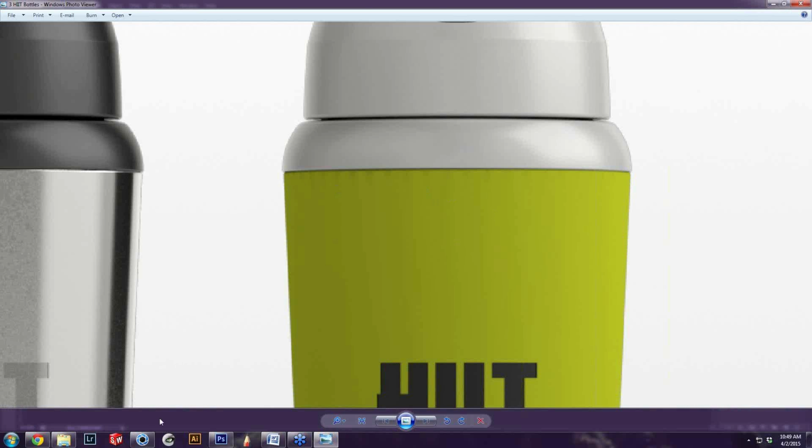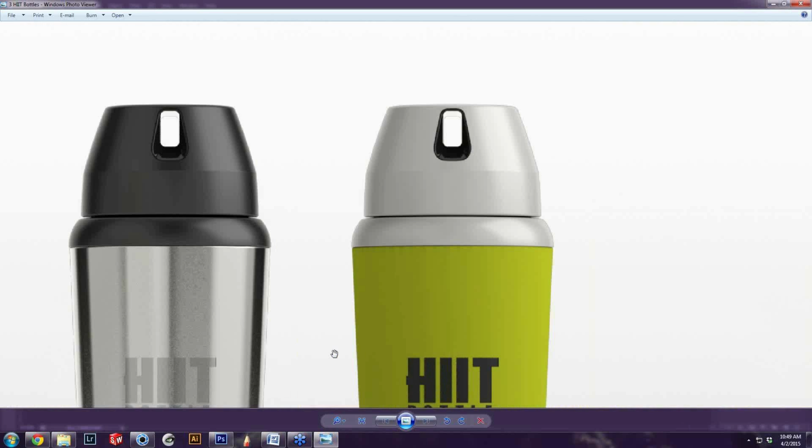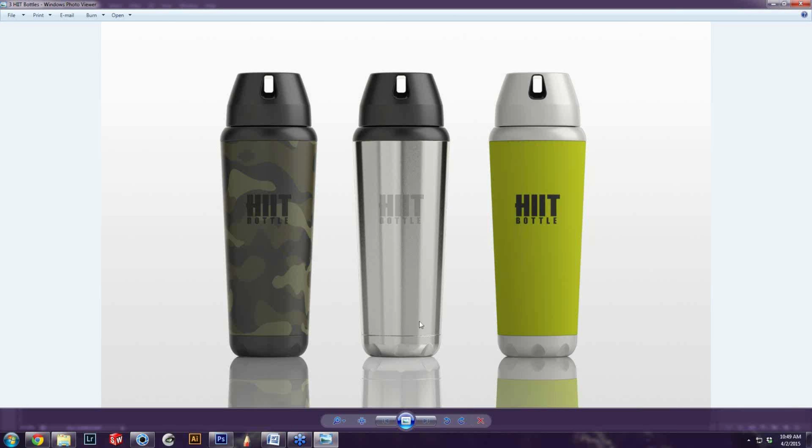But like I mentioned, if you are using KeyShot 5 Pro and have the NURBS feature available to you, you can click that NURBS button and it'll perfectly smooth out that round to eliminate any of those shadow artifacts that you would see. Also, you can try increasing your shadow quality in your render settings, and usually that helps clear that up as well.